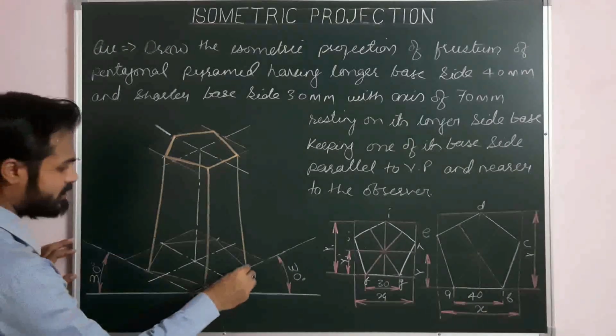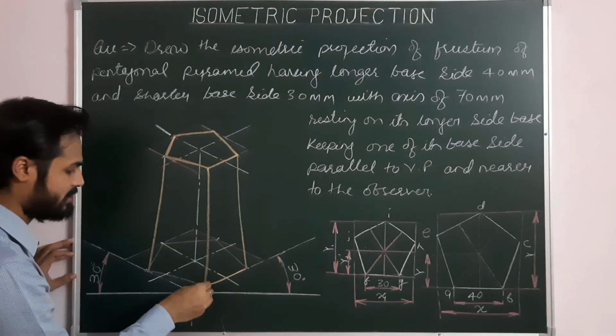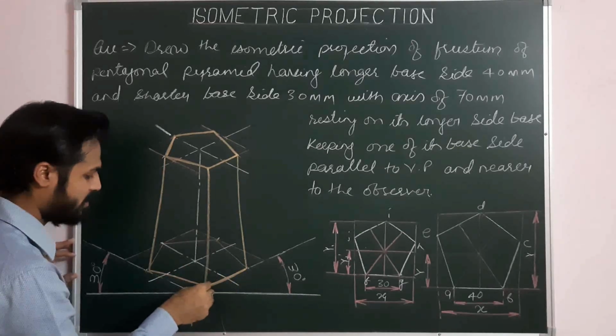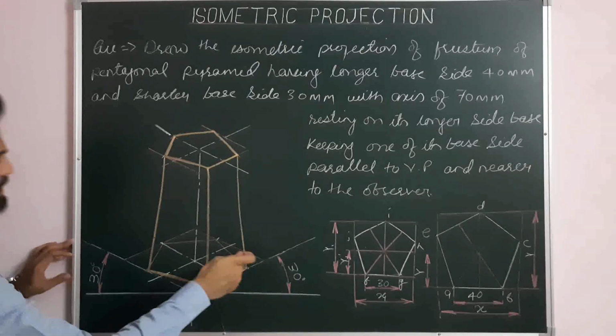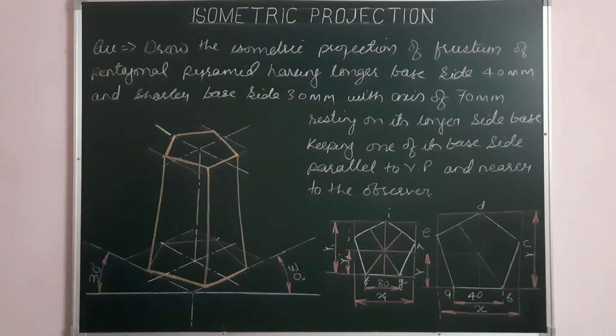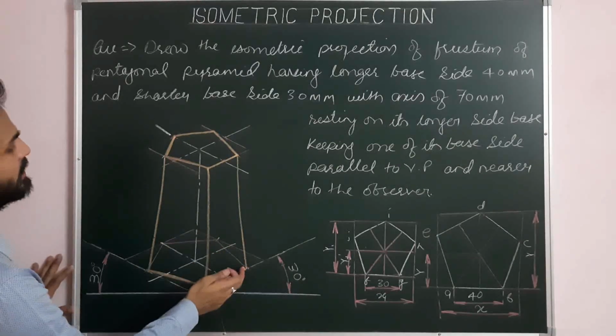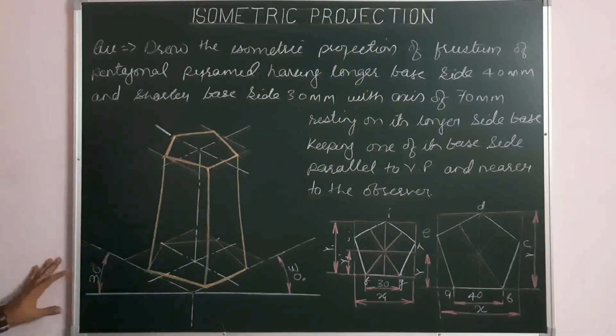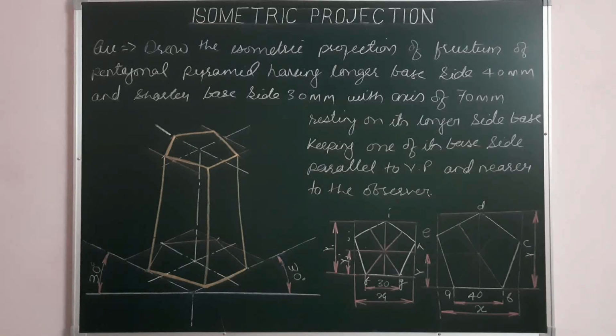Now on the bottom base, these are sides which can be viewed from the direction of observation, and all other sides, first side, second side, and third side, also these 2 generators are hidden generators, so we will ignore them. So this is the final projection.